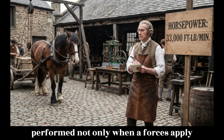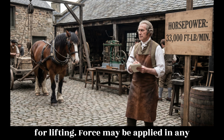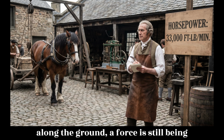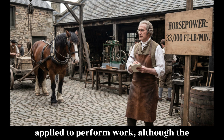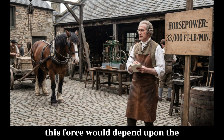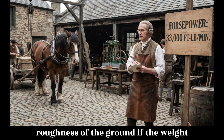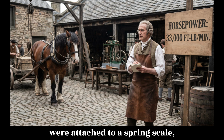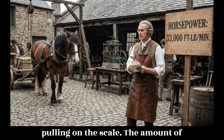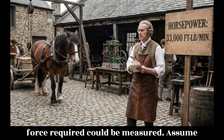Work is performed not only when a force is applied for lifting; force may be applied in any direction. If a 100-pound weight is dragged along the ground, a force is still being applied to perform work, although the direction of the resulting motion is approximately horizontal. The amount of this force would depend upon the roughness of the ground. If the weight were attached to a spring scale graduated in pounds, then dragged by pulling on the scale handle, the amount of force required could be measured.